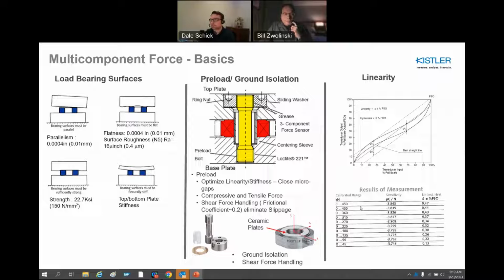A lot of times with piezoelectric sensors, you can do partial range calibration, and that gives you, in this case, this sensor was almost a 0.5% linear at full scale range. But if you go to maybe a 10% range, you're at 0.13% linearity. So you can optimize your linearity just by doing partial range calibrations, which might fit with some of the payload measurement ranges that you would need.